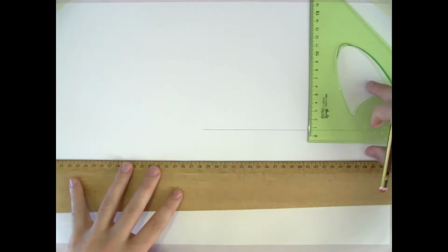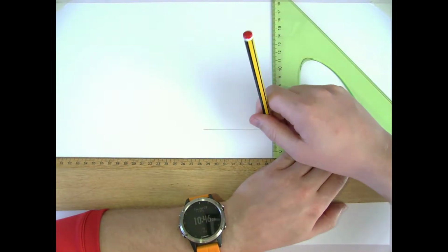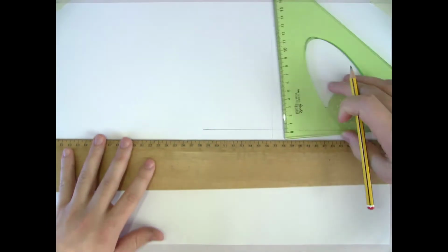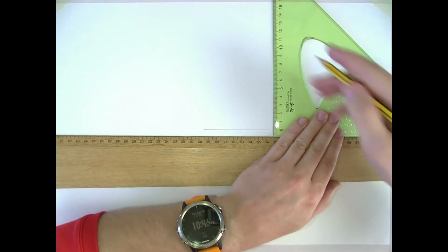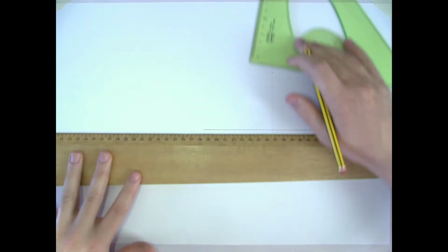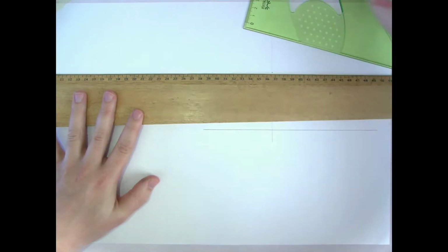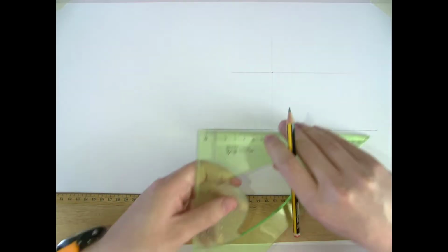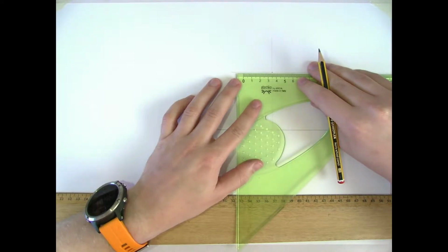So setting up our question, we're only asked to draw the elevation and plan. We don't need an end view. So we are going to start by setting up the inverted cone. I'm going to draw the central axis for the cone first, and that has a height of 70. Mark that up. And the radius for the base of the cone is 35, so that's going to be 70 across the top.